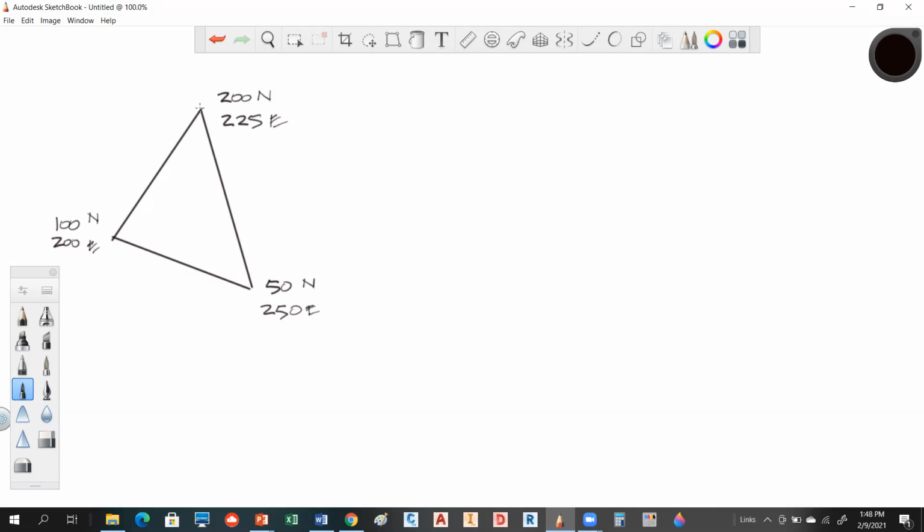So we'll call those points 1, 2, and 3. Again, notice north is up here because that's getting higher. What you do is you can start with either the northings or the eastings first, it doesn't matter. I'm going to start with the northings, starting with point 1. So this is 1, 2, 3, and then I have to repeat 1.